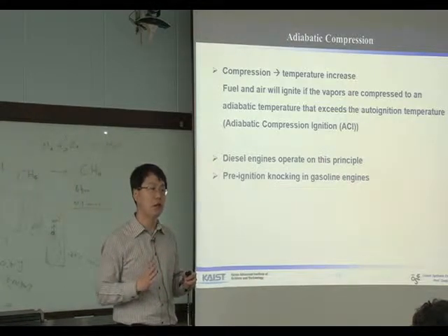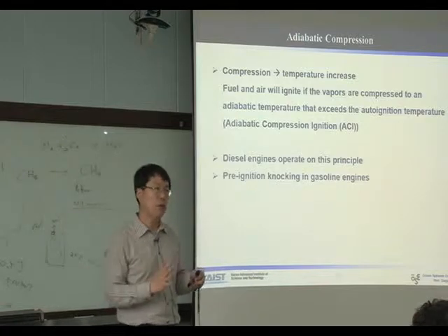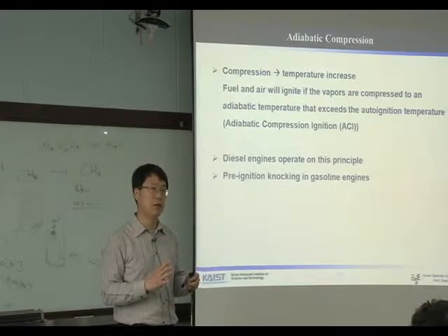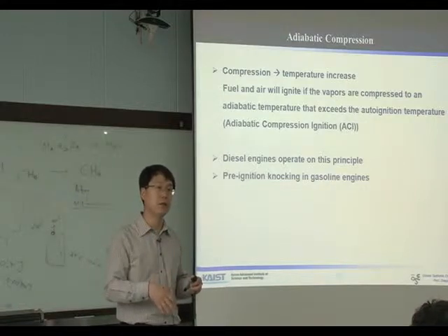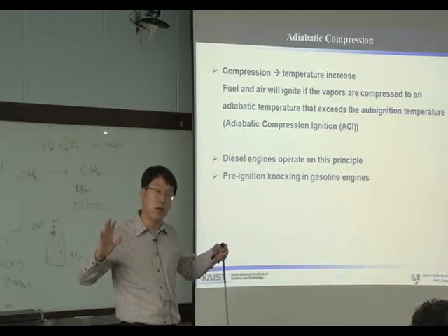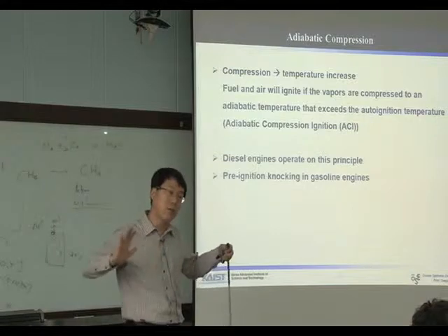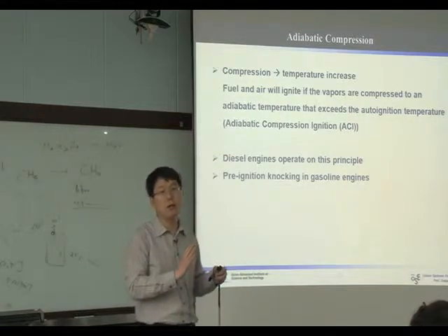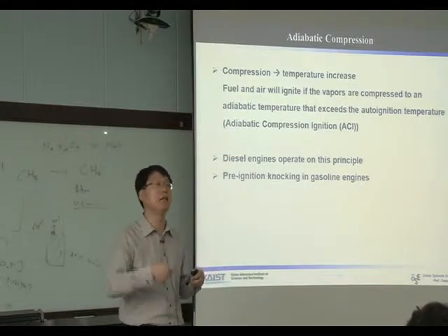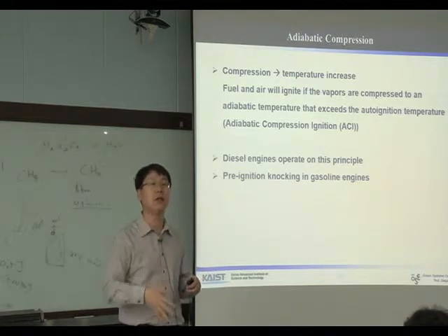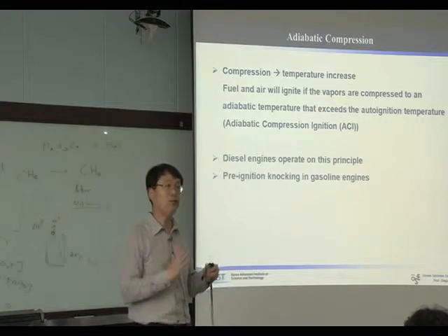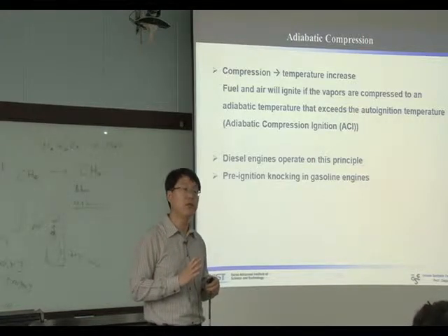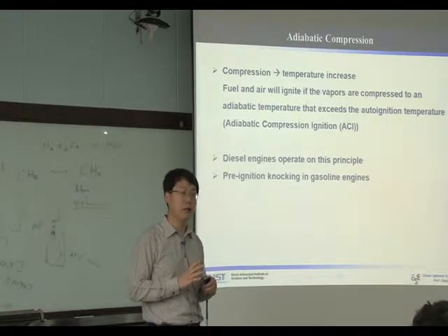So the compression work results in the increase in the internal energy. We give work to the gas, so the gas has no time to release the energy, and the temperature of the gas increases. So usually compression means temperature increase, always.